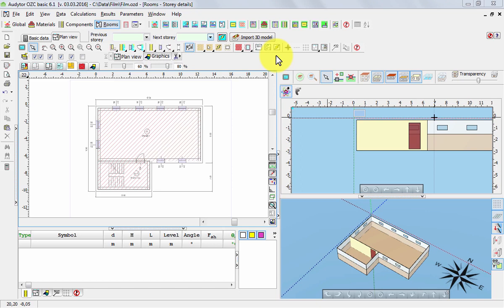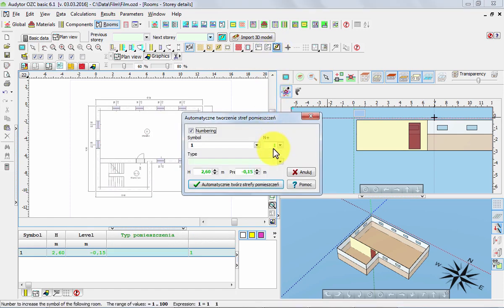So a lot of people prefer the second method because it's still quite fast, but by clicking the rooms in the right order, you can control the order of the rooms. In this case, we have only 2 rooms and quite specific, so let's use this last method, and then we will be able to renumber the rooms manually.